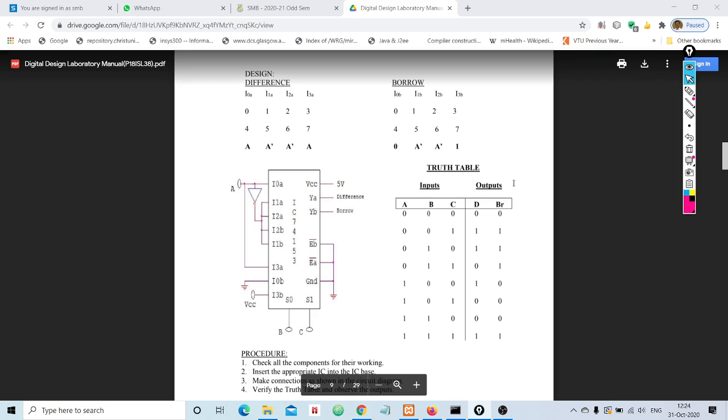For better clarity, I will keep it like this so that I can get a complete view. As I said, we are focusing on multiplexer A here, and these are the input lines of multiplexer A. Just write continuous numbers starting from 0, 1, 2, 3, 4, 5, 6, 7. Why should it start from 0? Because look at the truth table. Usually the decimal equivalent of the binary will be 0, 1, 2, 3, 4, 5, 6, 7. These are nothing but the decimal equivalents of the binaries.